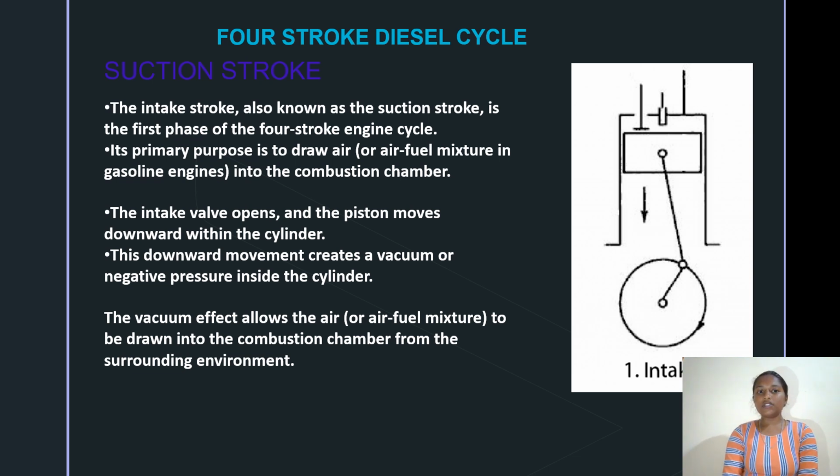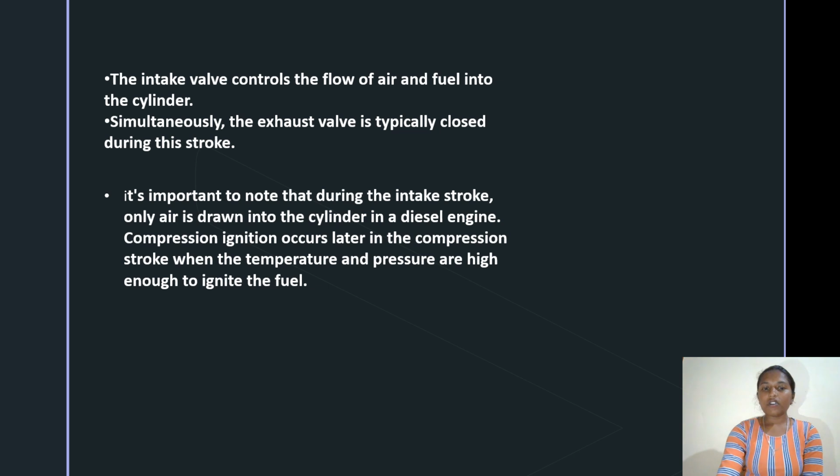After this stroke, there will be the next stroke. During this stroke, only air is drawn into the cylinder in the diesel engine. Compression ignition occurs later in the compression stroke when the temperature and the pressure are high enough to ignite the fuel.